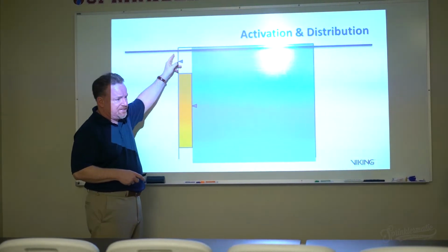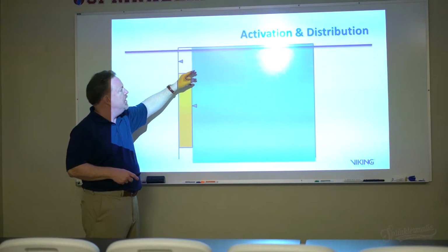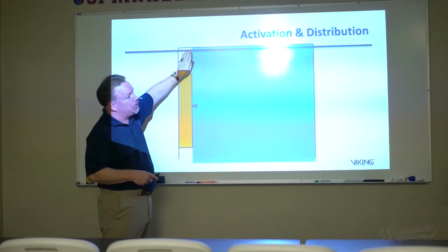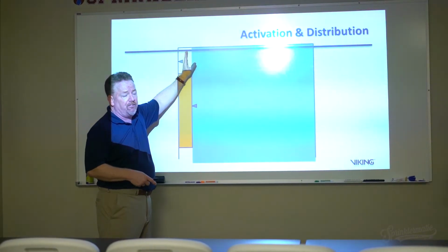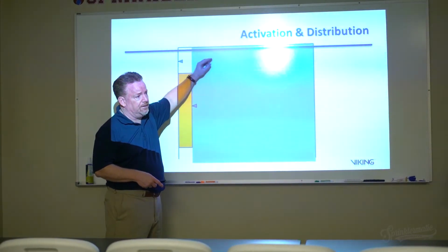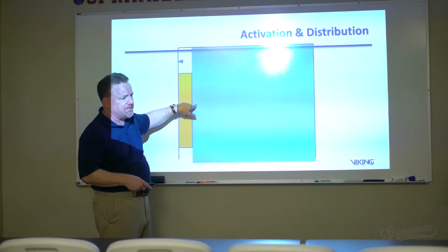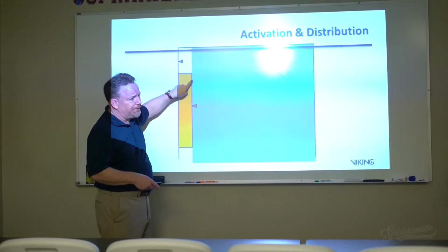And that's really a critical thought process that gets missed when we start overanalyzing shadow spaces, shadow areas. When we start saying, oh my God, there could be a fire that starts there, and there could, who knows? But what's the fire going to do? It's going to move out here. Eventually, it's going to activate this sprinkler, and what's that sprinkler going to do? It's going to control it.